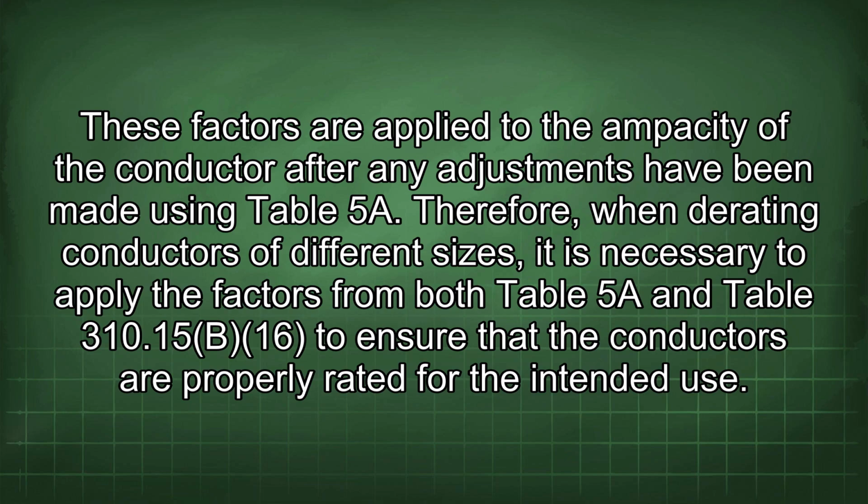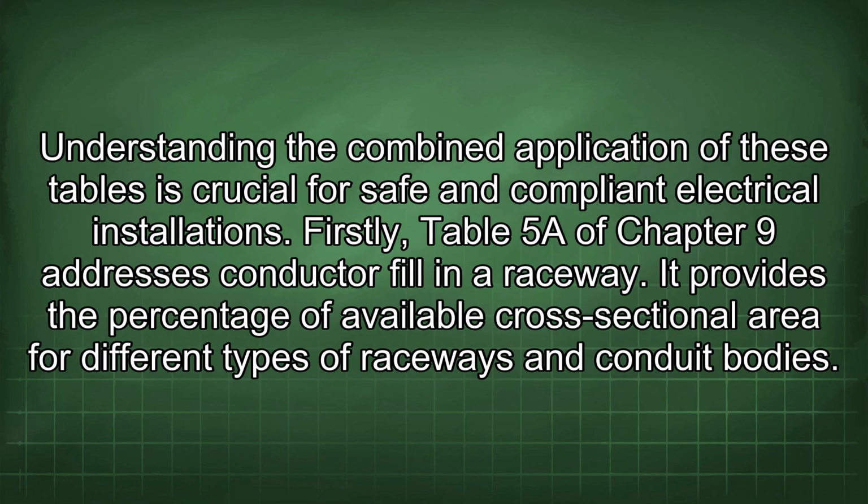Therefore, when derating conductors of different sizes, it is necessary to apply the factors from both Table 5 and Table 310.15(B)(16) to ensure that the conductors are properly rated for the intended use. Understanding the combined application of these tables is crucial for safe and compliant electrical installations.